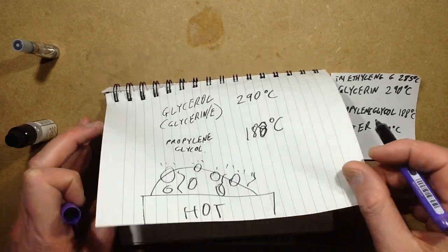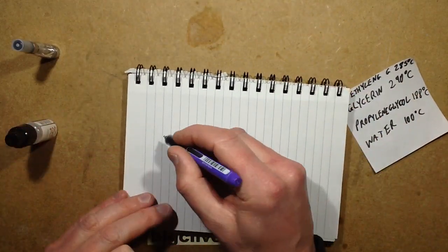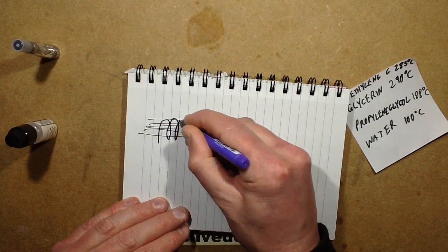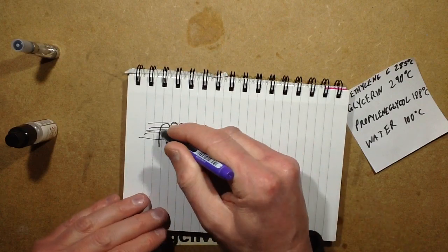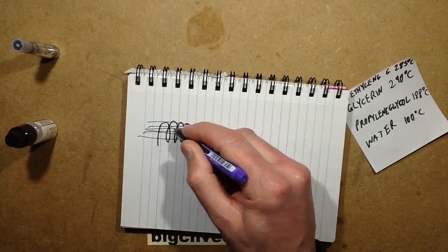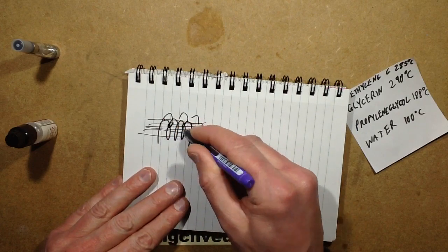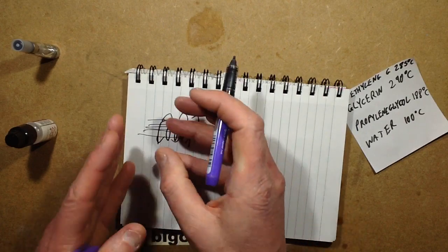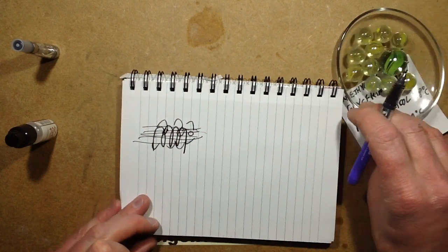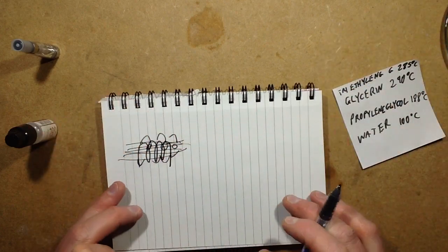And in the case of an electronic cigarette, the way it's doing that is it's got the strands of the wick, and it's got a coiled heat element around it, and that's heating. The liquid's wicking up the wick and getting taken into the heat element. It's getting boiled, and those bubbles will form all over the surface of that and then burst. And as you're drawing the air through, you're drawing through those tiny little microscopic spheres, those little beads, those little lenses of glycol, and that's what creates the fog in the air.